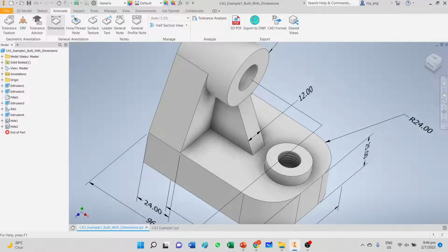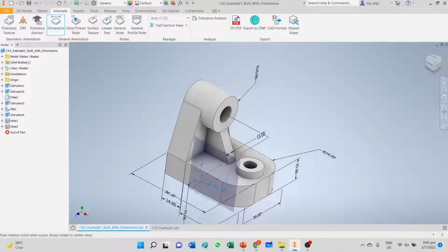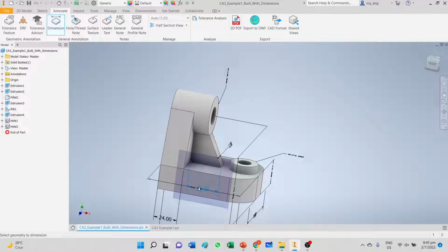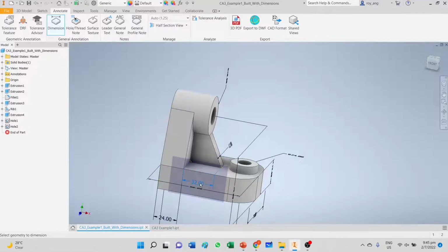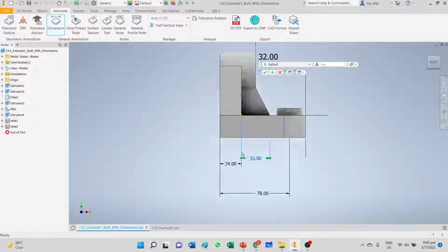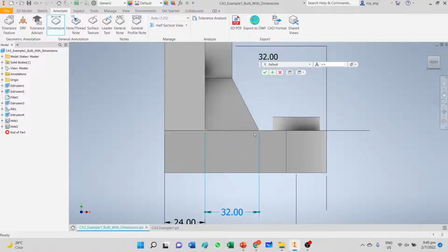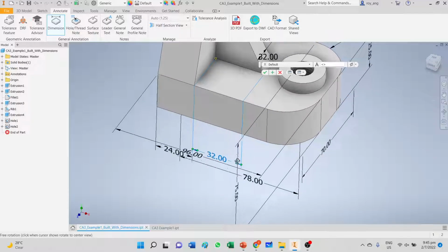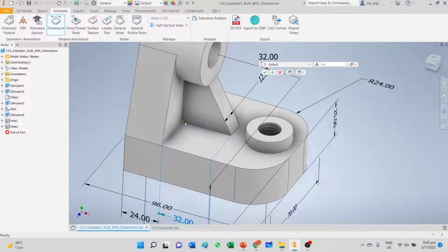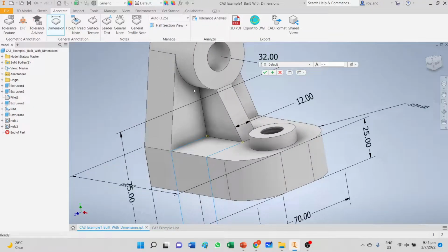Excuse me, sorry, let me try again. I click this point and this point, so it goes to the point, and then I right click. I would say I'll choose this surface. Okay, and the bottom width of the rib is 32 millimeters. Okay, so these are the two dimensions that are required for me to create the rib.